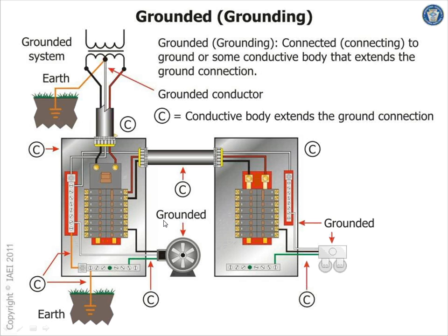The reason we ground the equipment is to put it all at the same potential, zero potential ground. So if you're grabbing one object and another object, you don't have 50 or 60 volts between the right hand and the left hand. Every time you have a difference in potential between any two objects and you connect them together with a conductive path, like my hands, you're going to have a current going right through somebody's heart. So safety is the main reason for grounding the equipment.